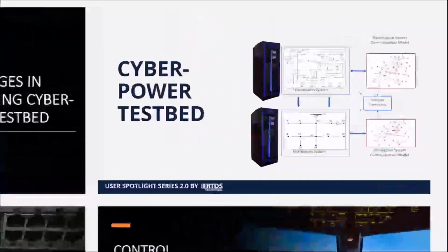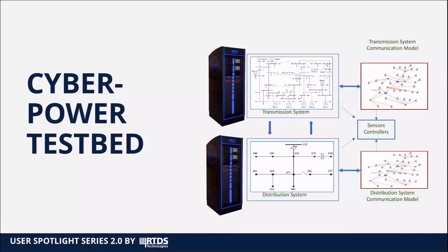And now let's talk about the cyber-power testbed that we have and are developing in our lab. So first of all, this is an overall picture of the cyber-power testbed. We are using RTDS, the real-time digital simulator, where we are simulating the transmission system and distribution system separately, and we have created communication networks using network simulators and emulators, connecting all the sensors and controllers, which take the streaming data from RTDS and give those data to control center applications via these communication networks.